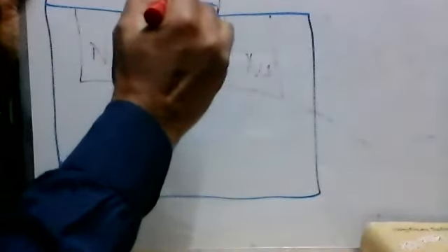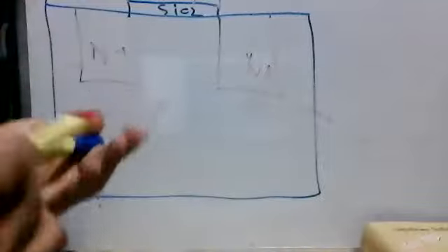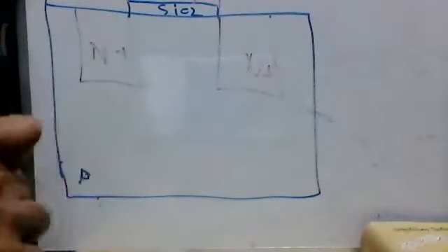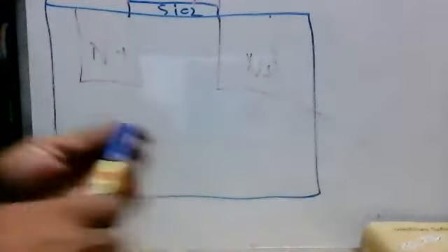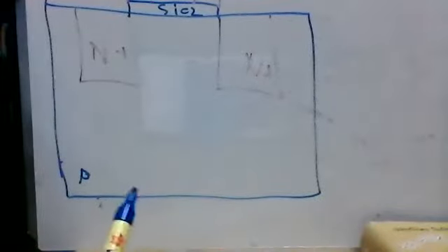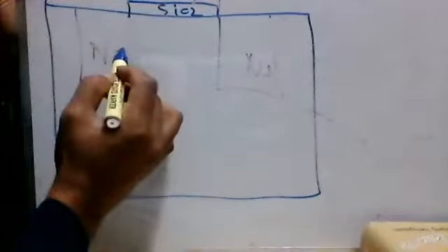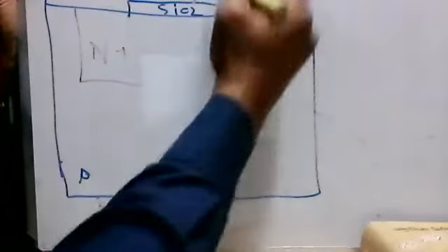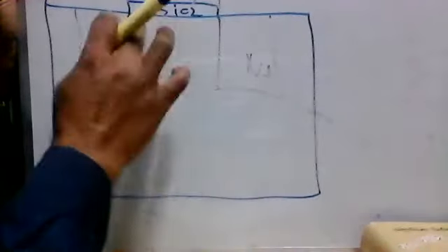This is a polysilicon. Now how does this transistor work? Now that's the question. The most important is how does it work? So the working principle is N plus N plus, but what we need to do, you see there is no channel here. There is a blank, and this whole thing is a P-type substrate.